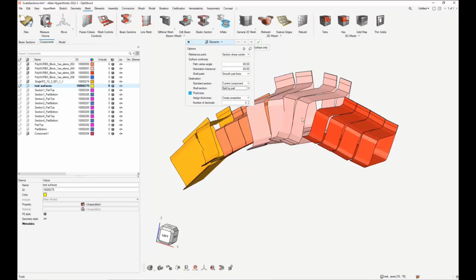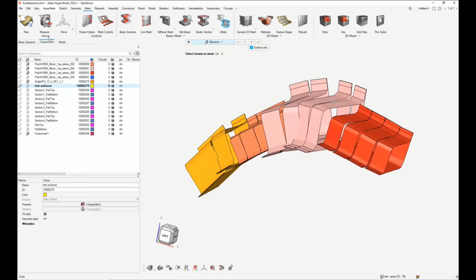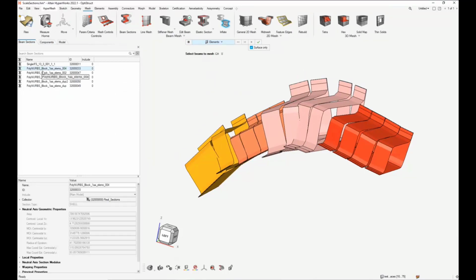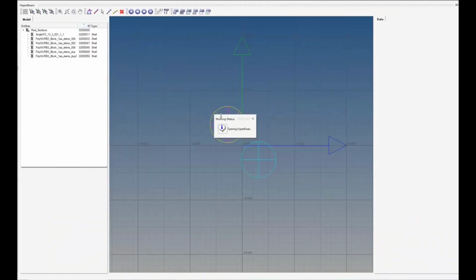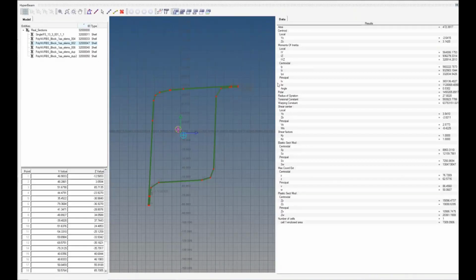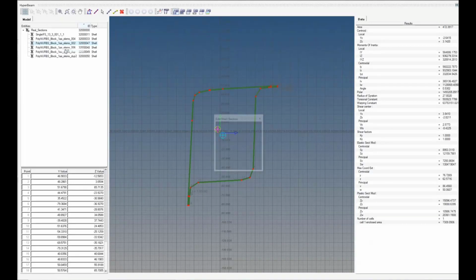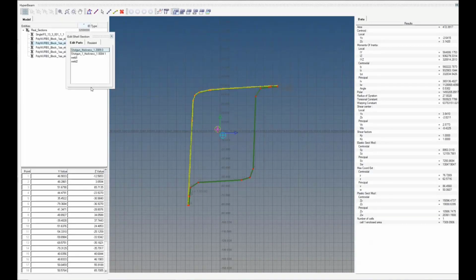But the concept of part, if you are not familiar with shell beam section, which is legacy data in HyperMesh: if we edit in HyperBeam, you can see that first of all, the actual representation of those thin wall sections is just point-per-point vertices. And each and every section has a concept of part, which is slightly different from the HyperMesh part.